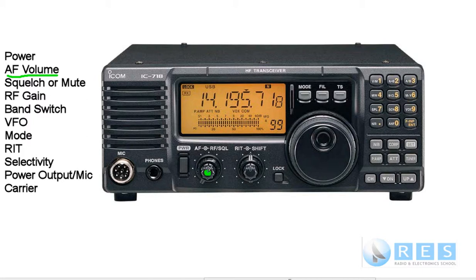The reason why it's that knob is this is a dual knob. There's a knob around the outside and there's one on the inside. How do I know it's the one on the inside which is the AF gain control? Because see the symbol there? The inside of the symbol is pointing to AF. So the inside of this knob, the internal knob, is the AF gain control, or volume of the receiver.